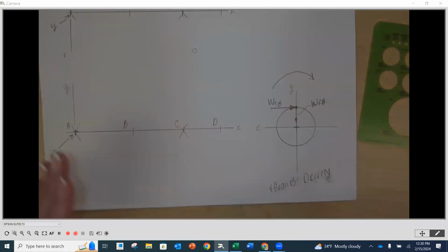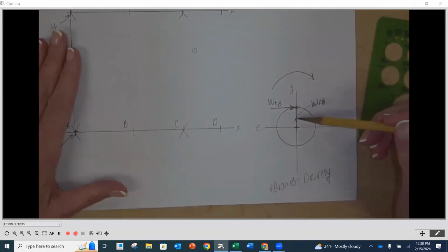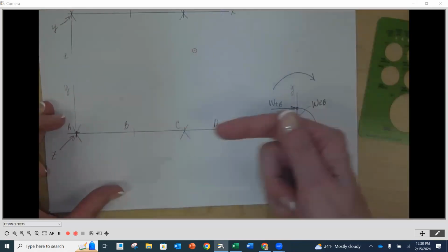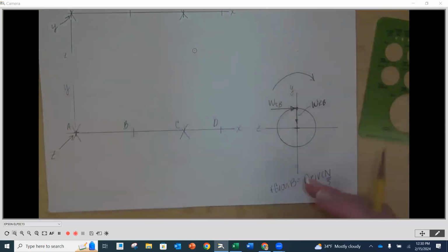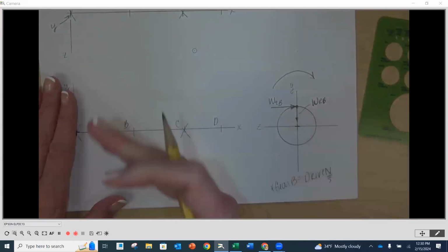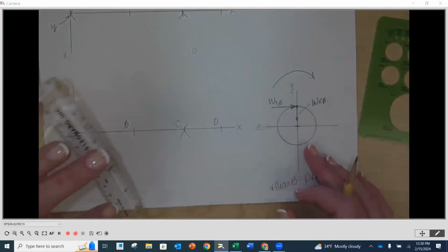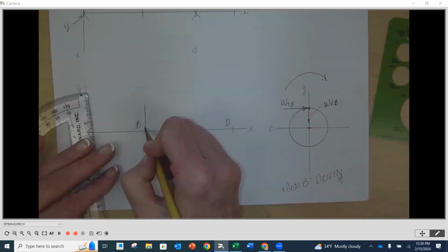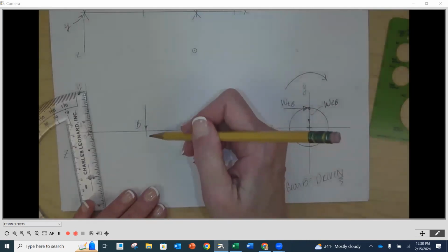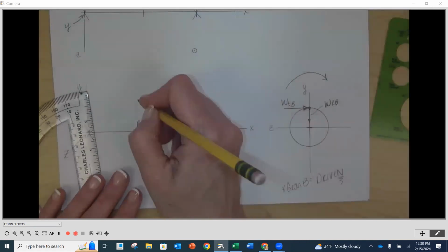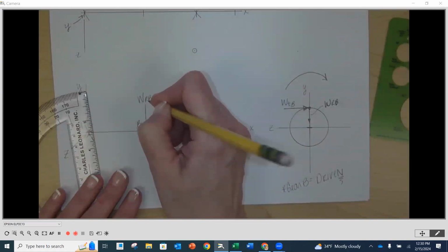Okay. Now let's put those onto our front and top views. So since we have our radial going down right here, when we take this and we tip it up on its end and we look down at the front view of it, our radial force is going to be seen in this view, okay? The tangential force is going to be in and out of the screen. It's going to be a point. So we're going to draw our radial force at B here going down. Whether you show it pushing down on the shaft or starting at the shaft and going below it does not matter, right? WR at B, my radial force.